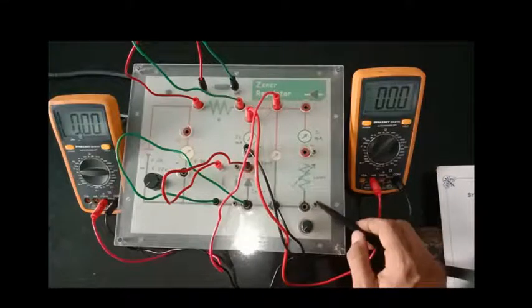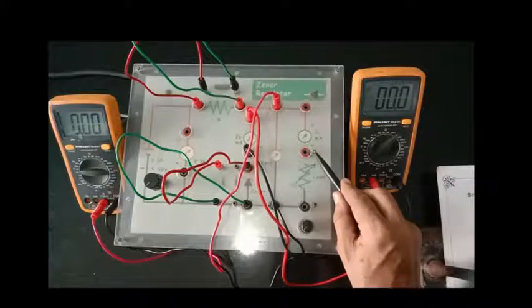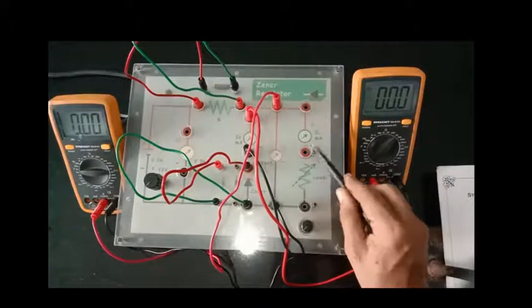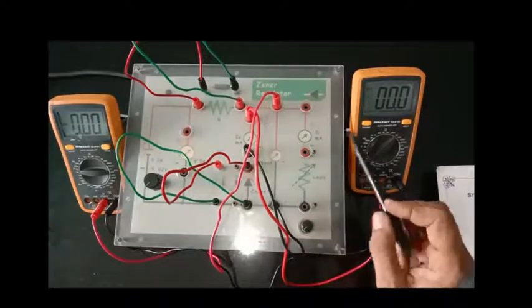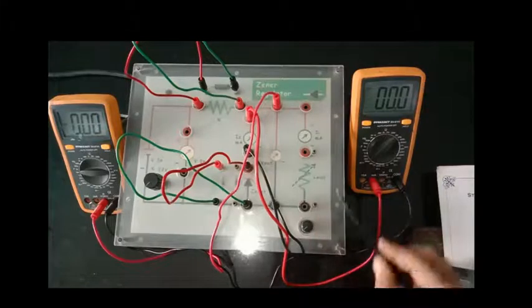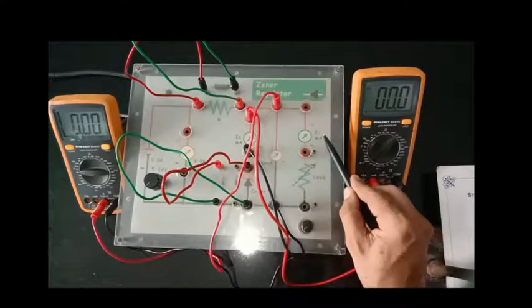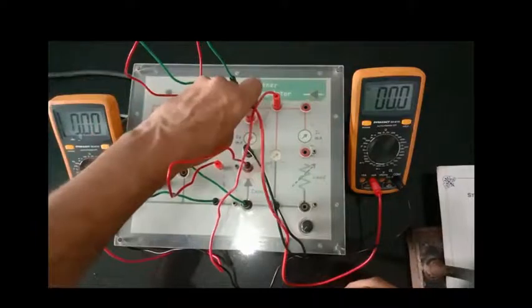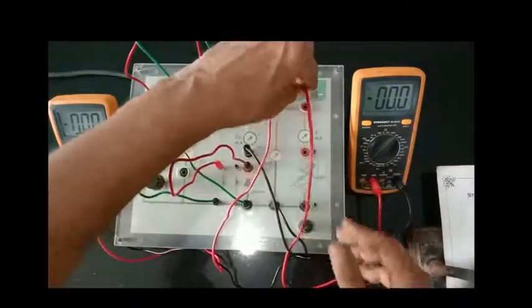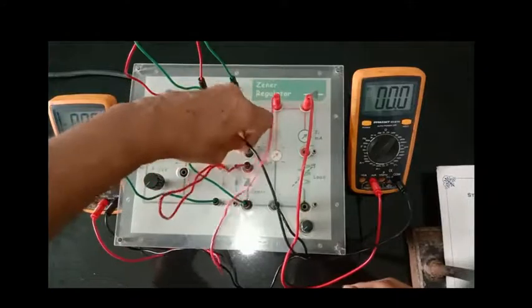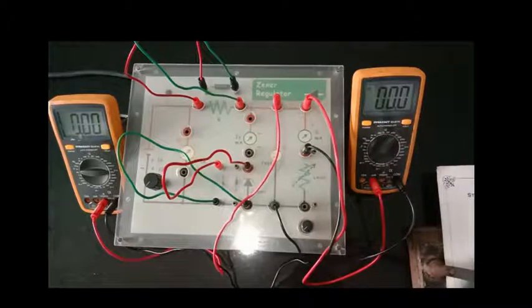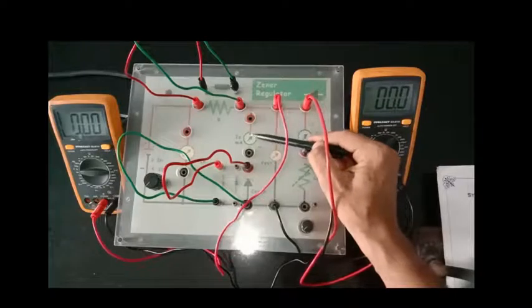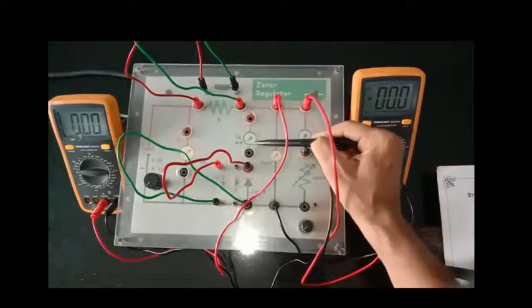So I will connect one terminal from here to here, so the load will be part of the circuit, but I think it is already part of the circuit, so there is no need for a connection between here and here. But now instead of IZ, I will measure the IL. So I will replace this IZ meter at the place of IL, because you have already taken the data of IZ, but the IZ should not be kept open, because the current meter is in general connected in series.